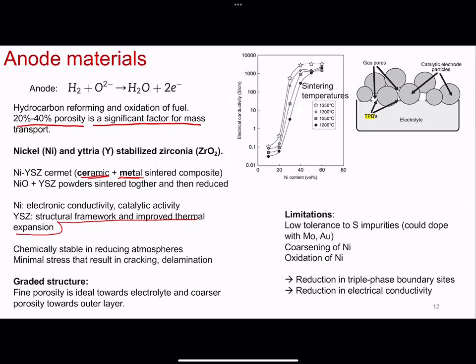Because you can imagine if you have, let's say, a metal as an anode, and then a ceramic as an electrolyte, and then a metal again as a cathode material, the thermal expansion at 600, 800 C is actually significant. And if you're making these thin films, you're going to initiate cracking because they're heating at different rates. The lattice expansion is at a different rate. So you're introducing a degradation in your fuel cell by the sheer fact that these materials are dissimilar, right?